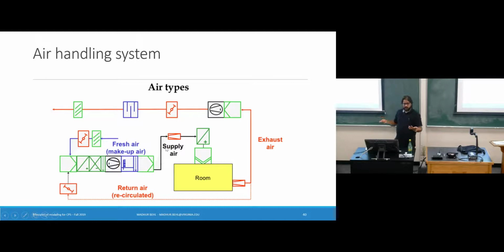If we are talking about cooling operation, the supply air is at, say, 55 degrees Fahrenheit. It's pretty cold. It's much, much colder than what most room temperatures are. So we cool the air down to 55 degrees Fahrenheit, and then we send it to the rooms through some other equipment as well, which I'll describe in just a second. In the room, this heat exchange occurs where we get the desired air at whatever thermostat setting we are at. I'm trying to locate where the thermostat in this room is.